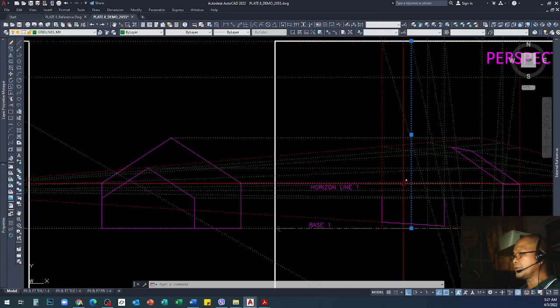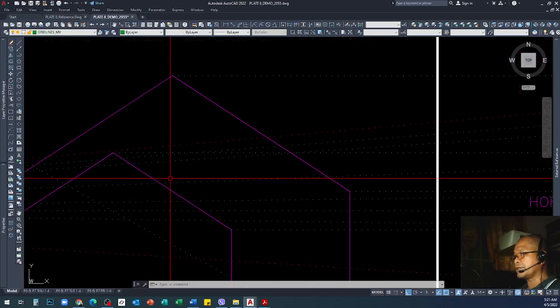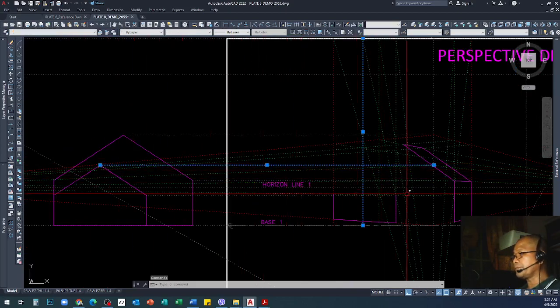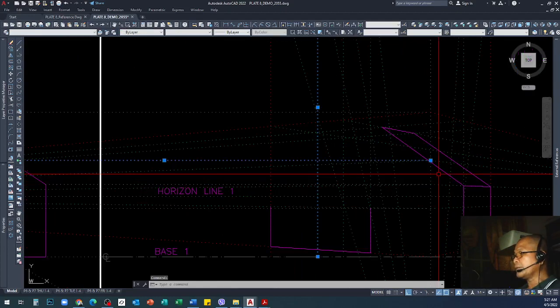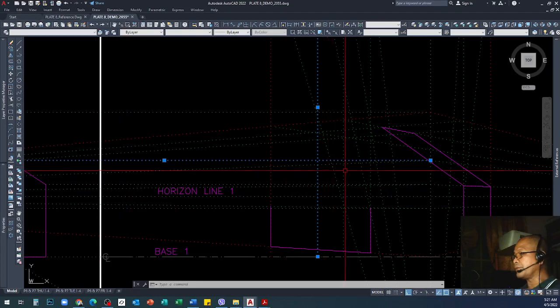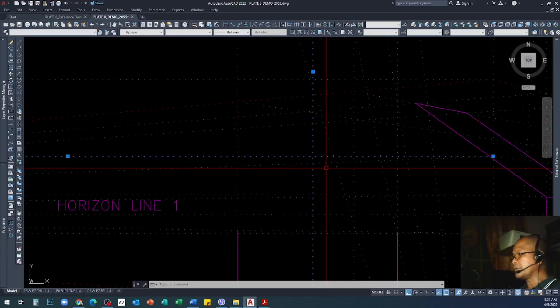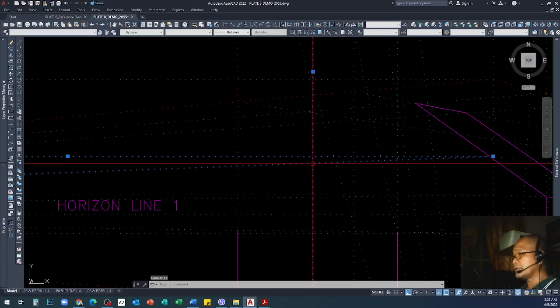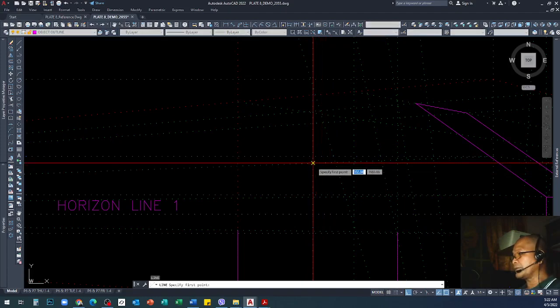So we need to know where the intersection is based on the height. The height is this one, and we already projected it to the left vanishing point. So the intersection of the two projected lines is the tip of that inclined portion of the object.